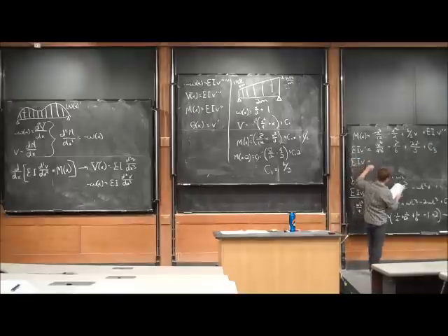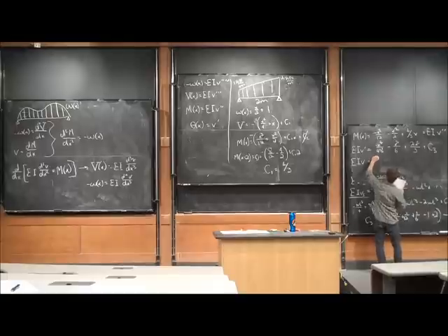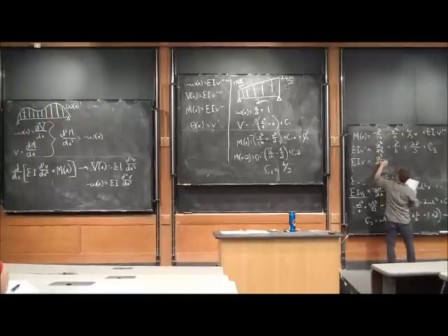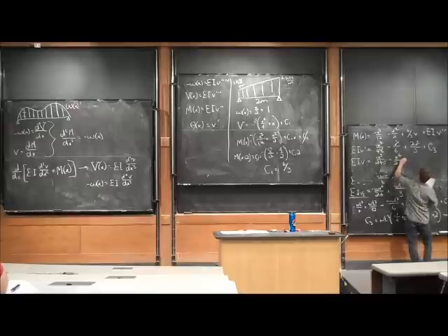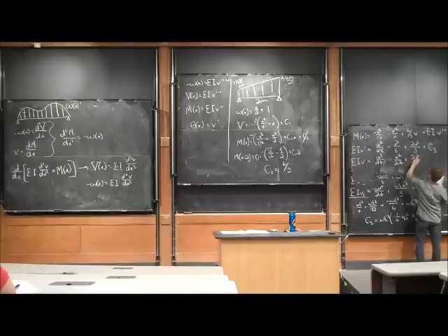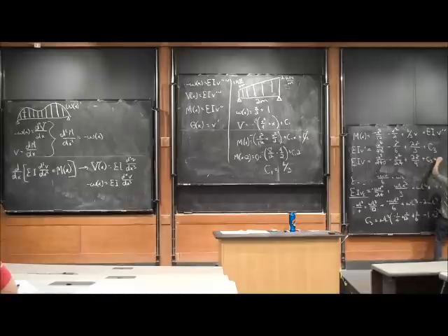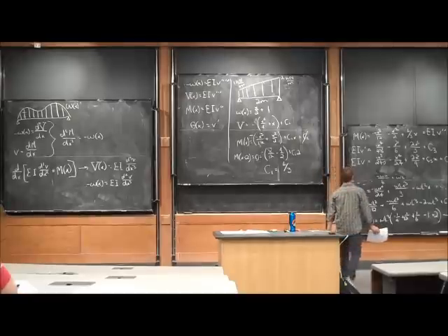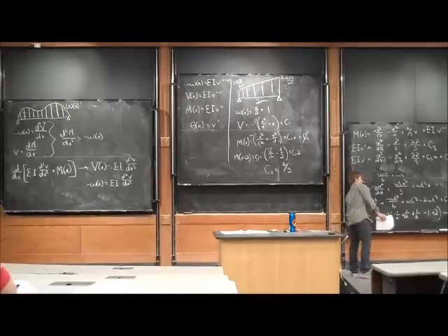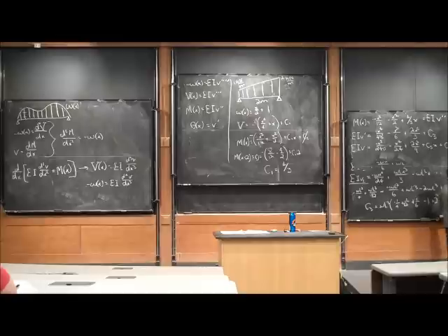My deflection equation is given by negative x to the 5th over 240 minus x to the 4th over 24 plus 2x cubed over 9 plus C3x plus C4. So you can see, even for a very simple loading such as this, this method for finding the deflection of the beam can be quite time-consuming and pretty tedious.